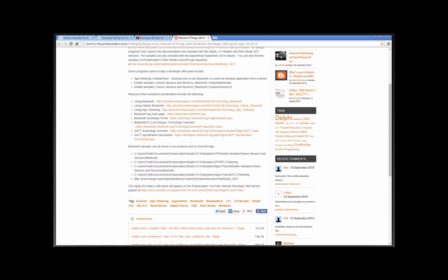The other thing is you'll use the Bluetooth Explorer. There's this little subscribe button. What that does is there's a method available on a Bluetooth LE device class that allows you to be notified if a characteristic value changes, if it has notification. You saw those attributes in the lower right-hand corner, and if notify is one of the attributes, you can query to see if it has a notify attribute. You can look at the code in the Explorer.